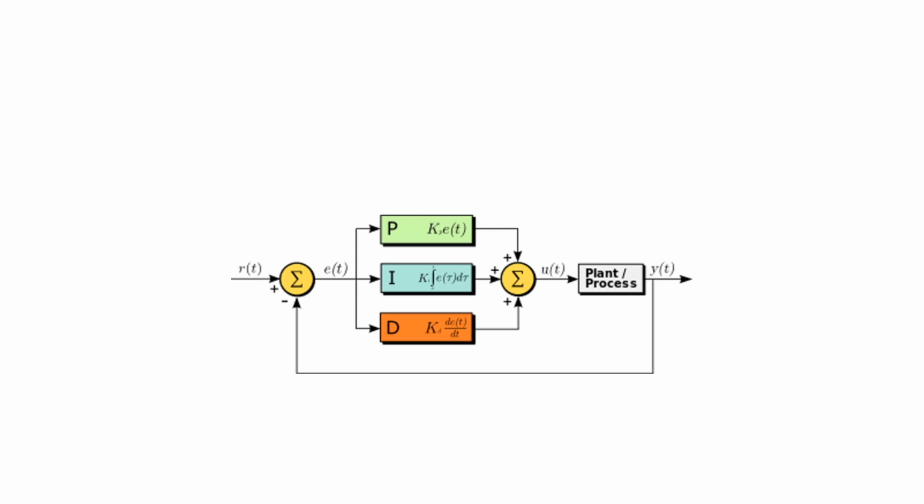While we haven't shown you the results yet, even with a well-tuned PID controller, we are faced with a conundrum. If the motor is too conservative at moving towards the desired set points or reference positions, we would have to increase the proportional or integral gains. However, doing so will increase oscillations or overshoot, because now the sensitivity to disturbances has increased as well. This will cause our sketcher to draw squiggly lines.